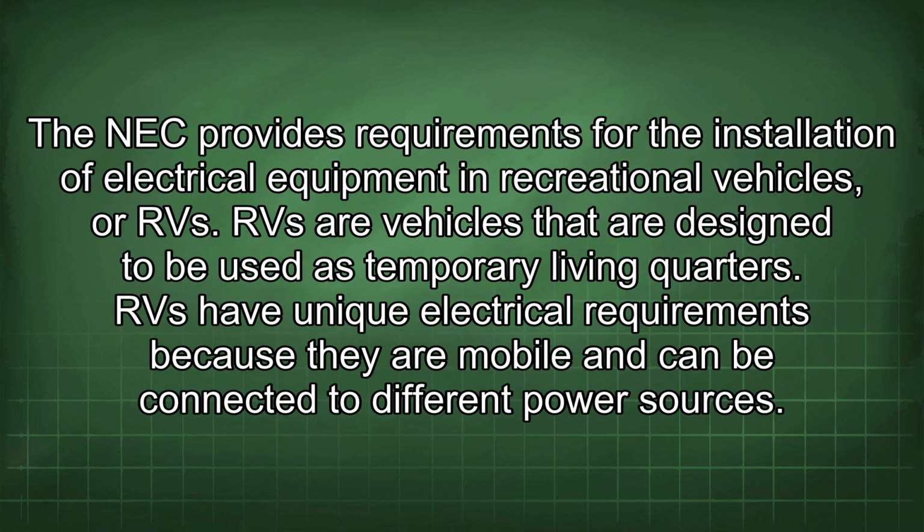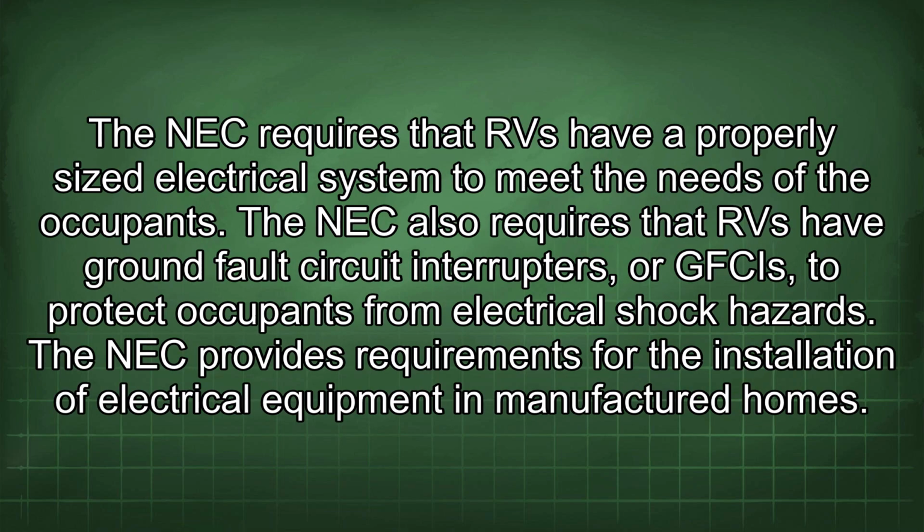The NEC provides requirements for the installation of electrical equipment in recreational vehicles, or RVs. RVs are vehicles that are designed to be used as temporary living quarters. RVs have unique electrical requirements because they are mobile and can be connected to different power sources. The NEC requires that RVs have a properly sized electrical system to meet the needs of the occupants. The NEC also requires that RVs have ground fault circuit interrupters, or GFCIs, to protect occupants from electrical shock hazards.